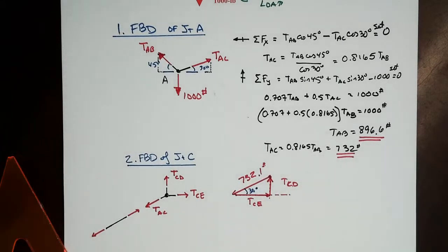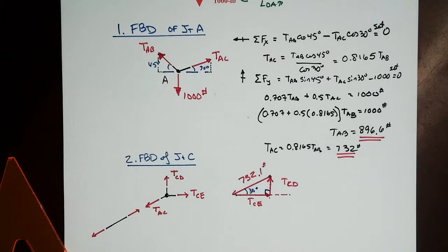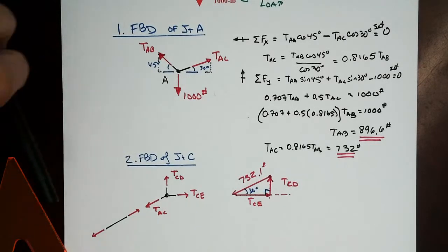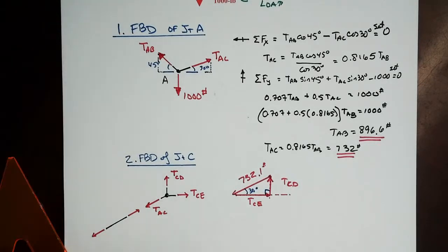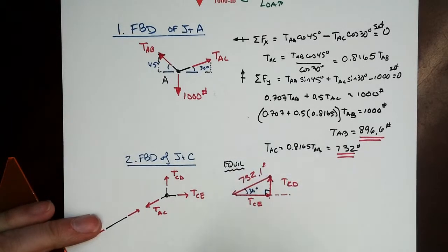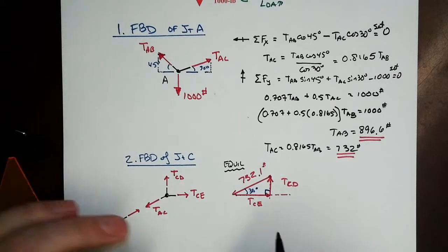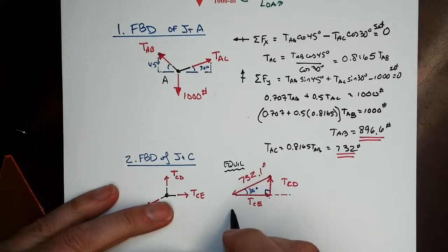And that's your force triangle. Now this is a very convenient force triangle because we have two orthogonal components. I designed the problem specifically to do this for us. All right, so this makes it actually pretty easy. This is our statement of equilibrium right there for that joint. And so now it becomes very straightforward.